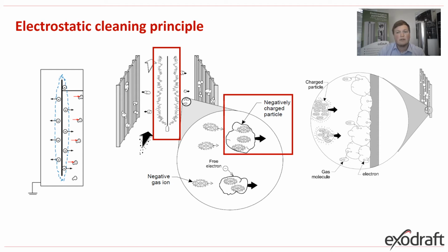Because the particles have the opposite polarity as the inner surface of the filter, they get attracted to the surface and attach to it like a magnet, thereby filtering the particles from the flue gas. Here you can see the buildup on the outer wall.